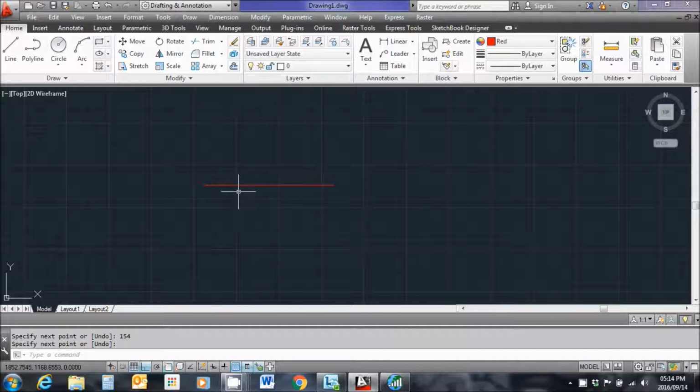In order to do that now, I need to multiply out the vertical scale so that when I draw a series of units in model space, I select the correct unit, which represents 1 meter. So now I'm drawing at a scale of 1 in 200. I'm drawing in meters, so what I'm going to do is to say 1 divided by 200 times 1,000. So one drawing unit in model space is equal to 5 meters at a scale of 1 in 200.